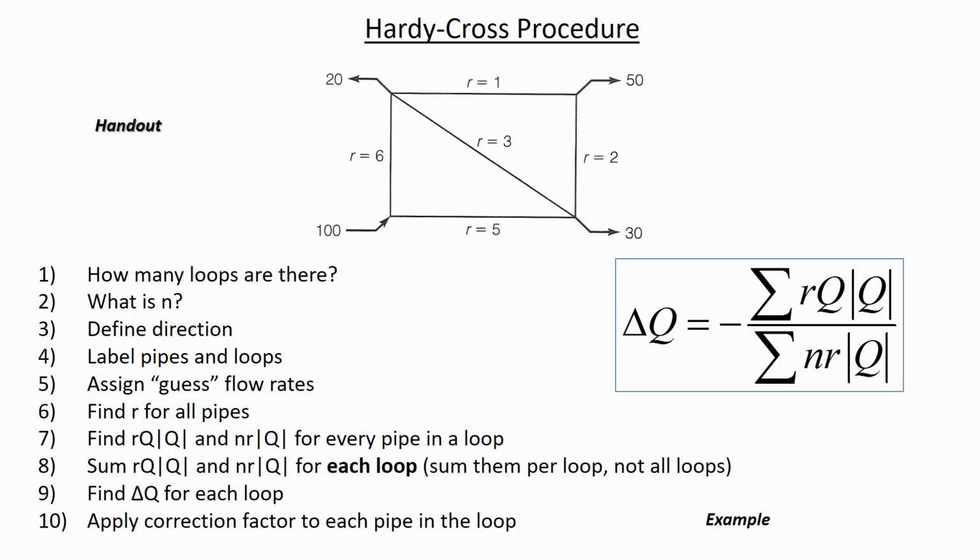Good question. That's right, we don't. We wouldn't count this exterior one as a third loop. There's only 2. The end value we're going to be applying, can you show me those loops again? Loop 1 is here, and loop 2 is there. All right? The end value is 2 because we're going to be using the Darcy-Weisbach method of accounting for pipe